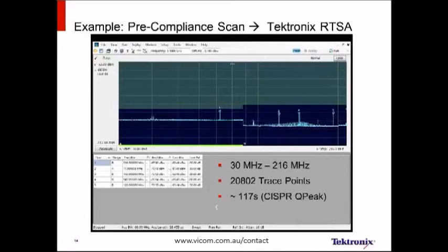And we did the integration, and we found that we only actually had 5 carriers identified. And with quasi-peak detection, none of these 5 were above the limit. They were all below the limit. But because I specified my threshold to be within 10 dB of the absolute limit, it still identified them as could be a problem for me. With this information, I could go back into my design and find out specifically where these frequencies are being used, and if necessary, take corrective action.